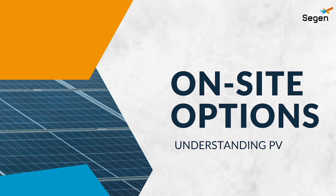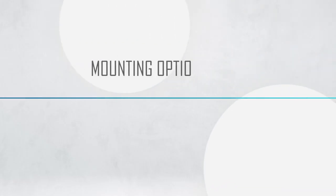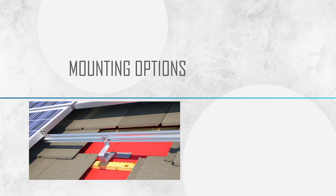So looking at the components of an on-site installation, a PV system can be split into 3 clear sections. Electrical, which is DC up to the inverter and AC afterwards. There's the mechanical components and also some accessories as well. In terms of mounting, there are loads of different options, but typically we'll see a panel held onto the roof by being anchored with roof hooks that are screwed directly into the substructure, such as the rafters.